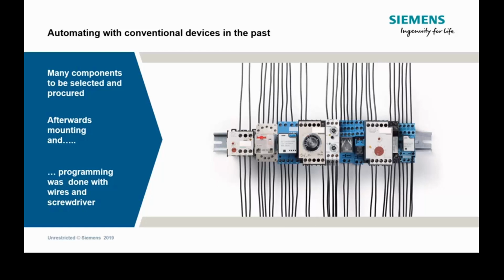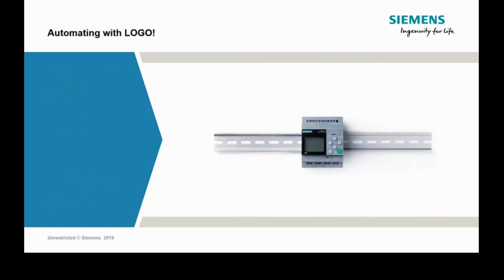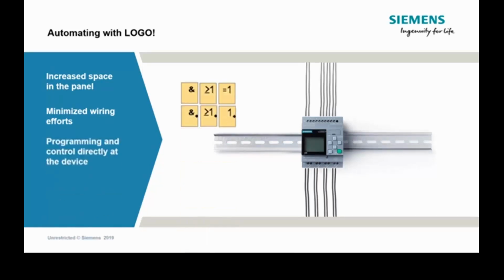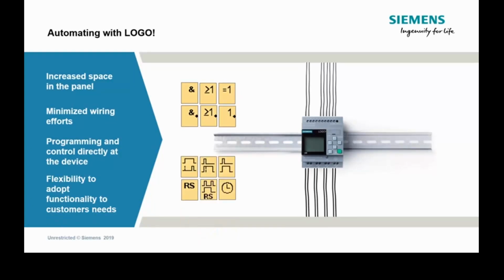And then also maintaining stocking levels of spare components from all of these different manufacturers and different suppliers, when we could actually start to rethink about our automation system and utilize a logo controller to replace all of those individual hardware components, save us a bit of space in the panel because of that, and also minimize on the wiring and thus the complexity within the hardware system. So any changes that any logical control that we want to now set up through the system, we do at a software level. So it makes it very easy and flexible to be able to change that logical path or introduce new functionality maybe at a later date.